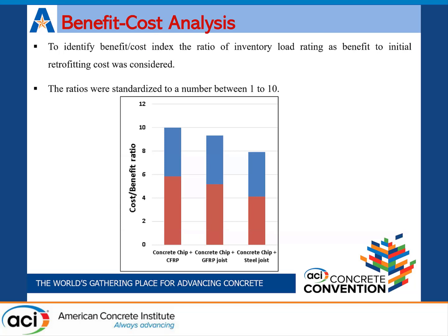Then a cost-benefit analysis was performed to choose the best retrofitting option. In the cost analysis, we considered all kinds of costs to retrofit the concrete deck, like material cost, labor cost, transportation, and traffic closure cost. Based on the cost analysis, concrete chipping plus CFRP is the most suitable option in this study.